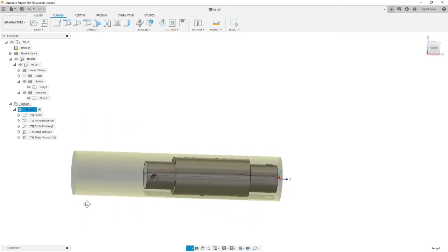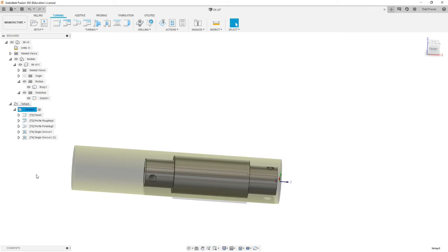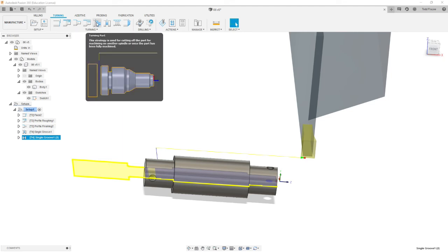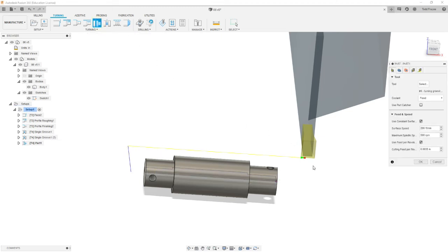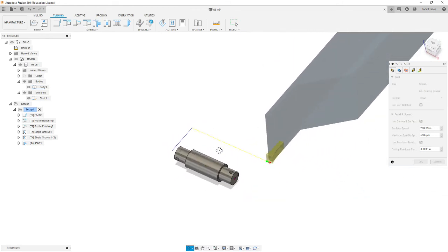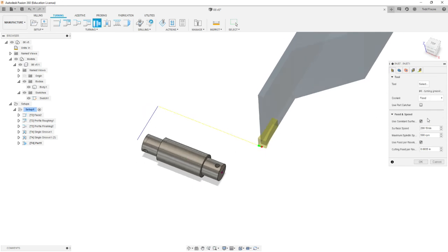We'll go ahead and use tool 4 for it. There are some other grooving tools in the library, but this one should just do fine. Okay, so we're going to select the turn and part command, and you can see in the icon it looks like the part itself is blue and the stock is gray. Select on that command, and it's going to actually automatically default to the back of your model, what you've defined as back on the setup. And we'll leave all these things at default.